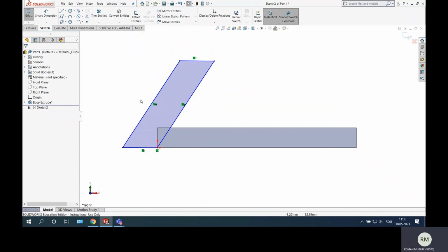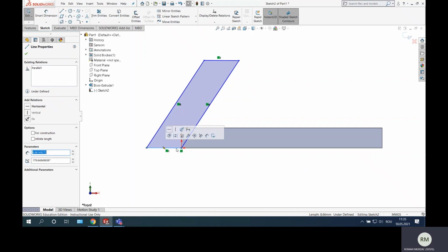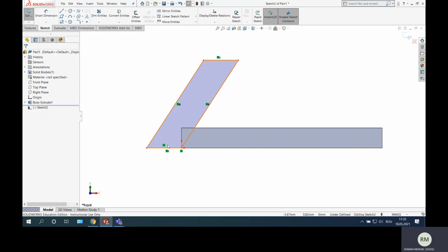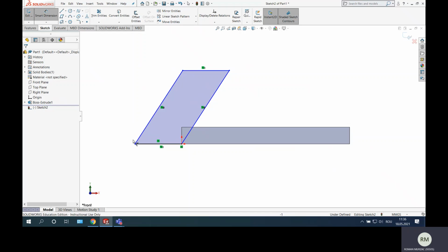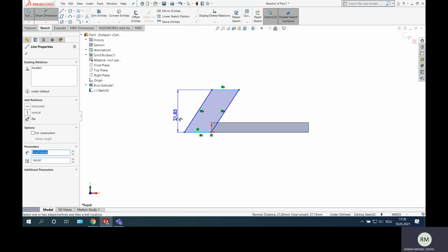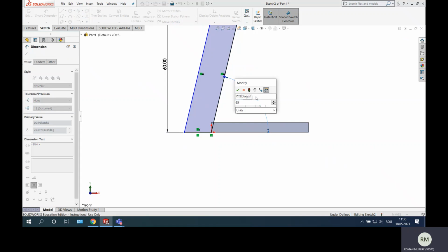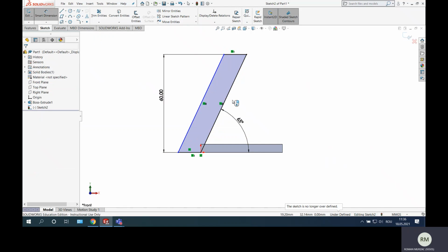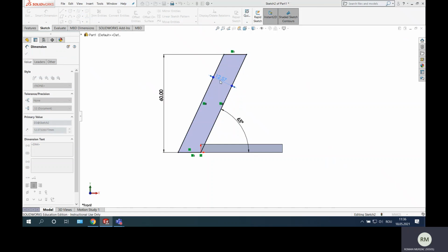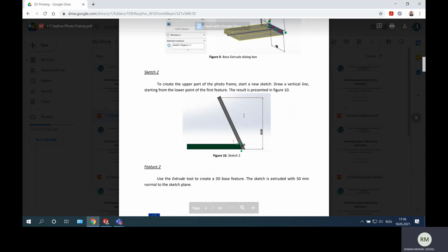Okay, so now I should put the geometrical constraints on this sketch, and I will say that this edge should be a horizontal one. Okay, now you see it's horizontal, so it can be moved just in a horizontal direction. Good. And what we know from the dimensions, this should be 60. The angle between this and this should be 65 degrees, and between this and this should be 5 millimeters, yes. In the same way this one, but I can check the dimension.